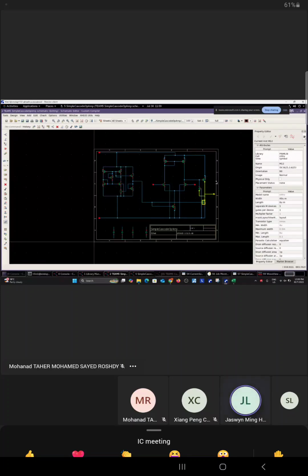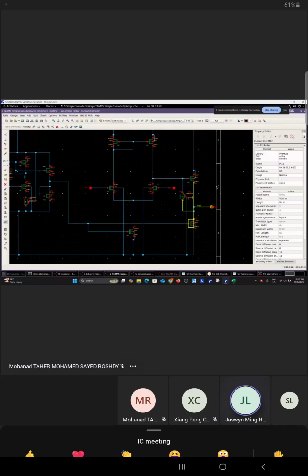Yeah, correct. Then you repeat this process for every single MOSFET. For example, if you have 10 MOSFETs in your whole circuit, you simply repeat this 10 times until you find the best point. So you start off with whichever value you have, then you plot V out against V in. Then for every single MOSFET that you want to tune, you repeat this process. Here we did 40.